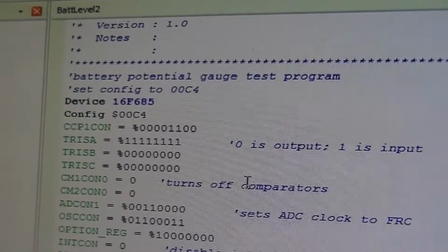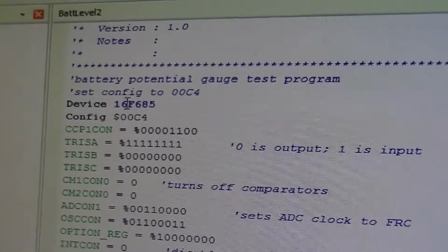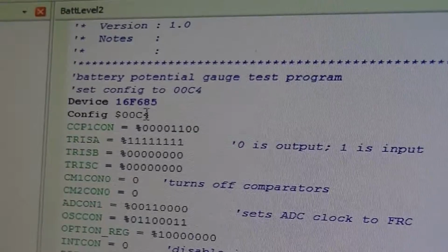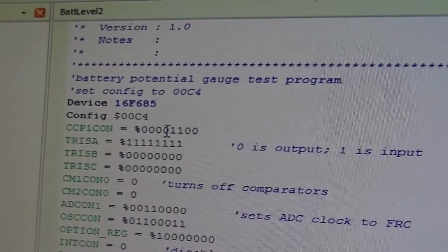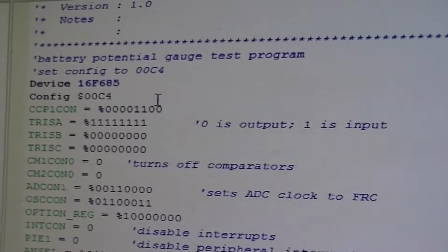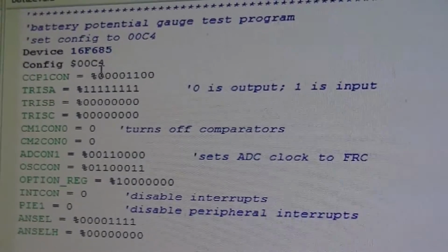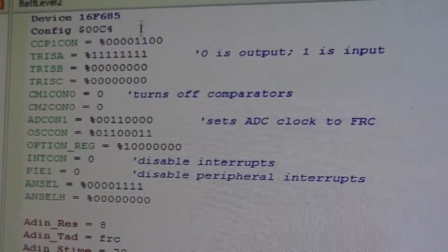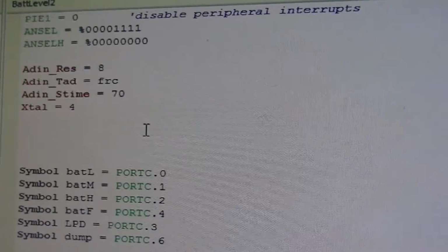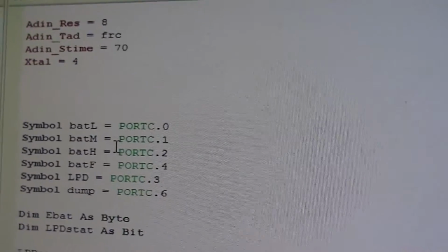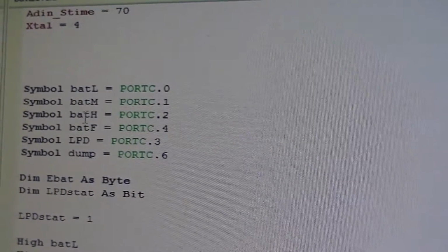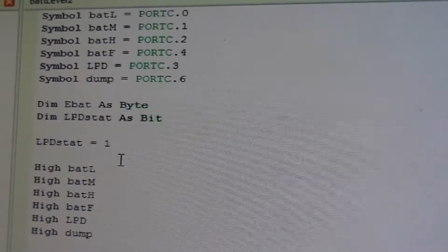And this is the control code that's running the PIC. There's the device statement, the configuration thing, which for some reason isn't working. It isn't passing the configuration word setting to the programmer, which is annoying. And there are the register configurations, miscellaneous blah, aliases just to make the code easier to read.